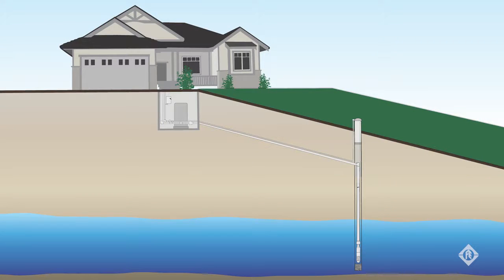Let's take an example of a pump for a 3-bedroom house with a well that has a flow capacity of 15 gallons per minute. With this information, we usually suggest a 10-gallon-a-minute pump, which will have to produce 10 gallons a minute at pressure from lower than static level. The 15 gallon per minute would have been established from the driller's log if we're installing a new pump and well.